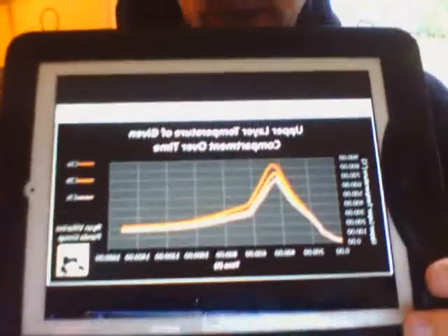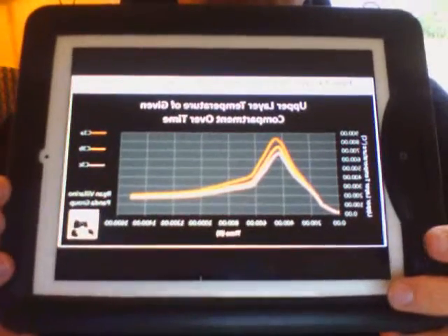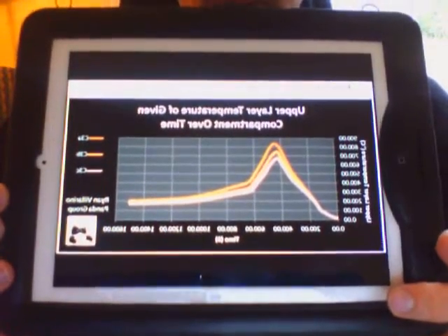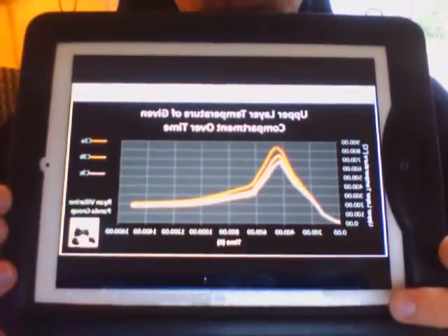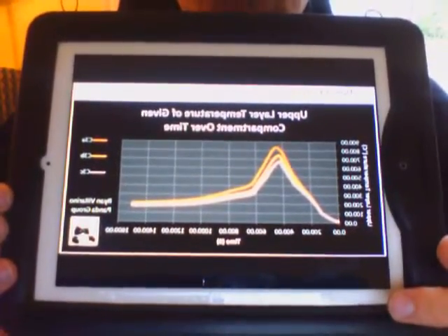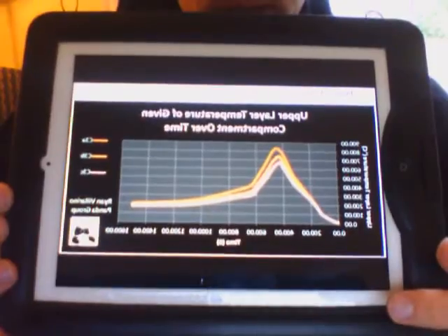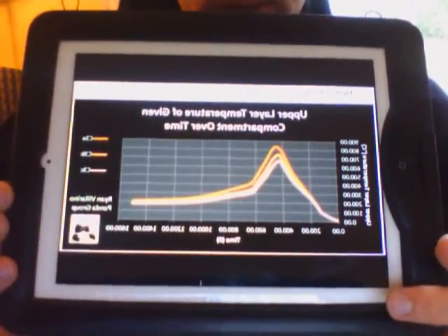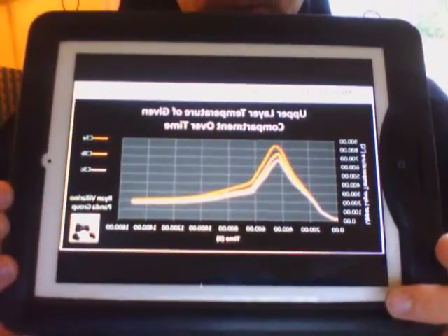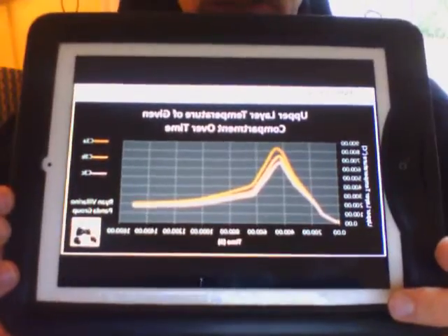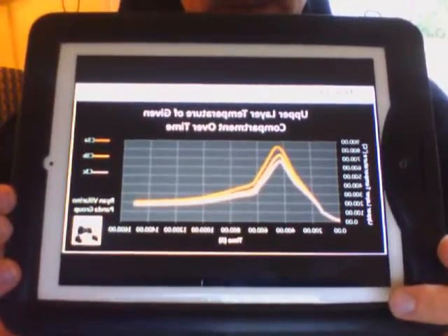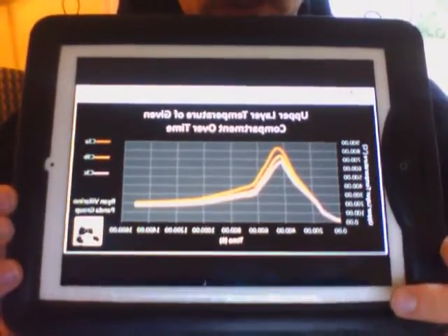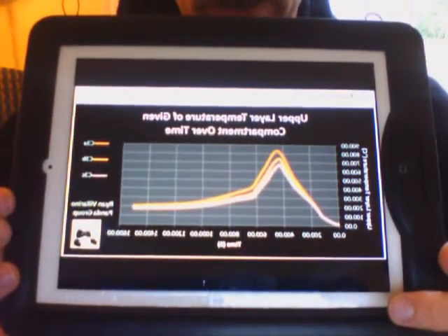For that, first thing we'll show you is the upper layer temperature given off by these 3 rooms. Now, what was a little interesting to note here is that last model, C3C, is the one that actually produced the lowest temperatures. So we had two vents venting to the outside, and that was able to produce lower temperatures than anything venting into a hallway and then venting outside.